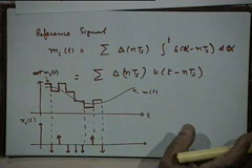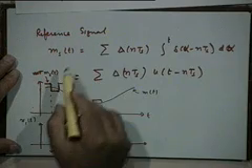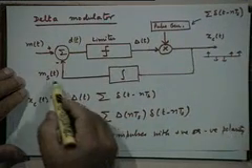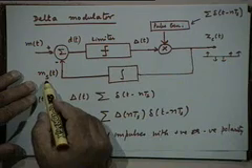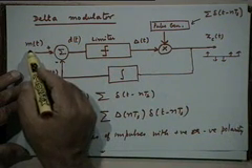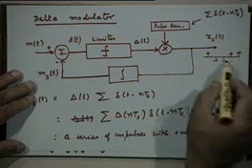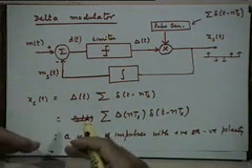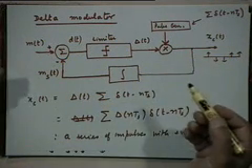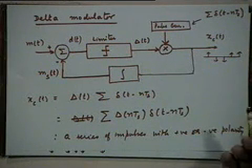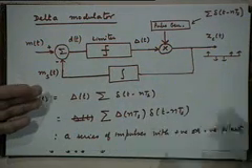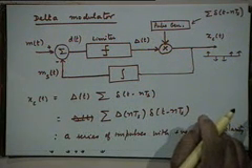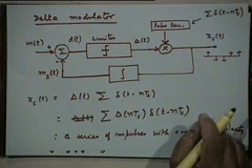This is how the delta modulator works. Basically, the reference signal is a staircase kind of approximation to the actual signal, and in this way you generate a series of positive and negative impulses, right? And from this description, it is also obvious how we should demodulate. Just pass it through an integrator, because that will produce the same staircase approximation at the receiver. Whatever we do in the feedback part can be done at the demodulator to produce the same staircase approximation to the message signal m(t).